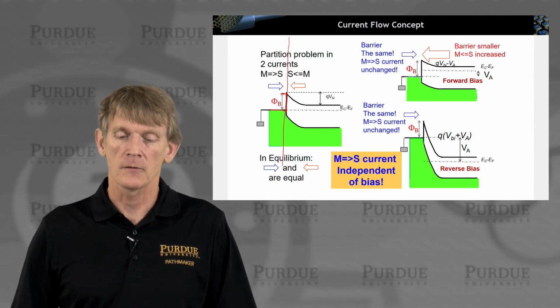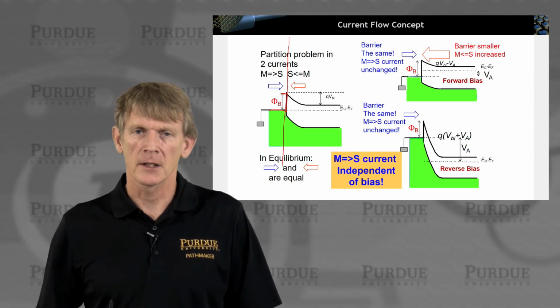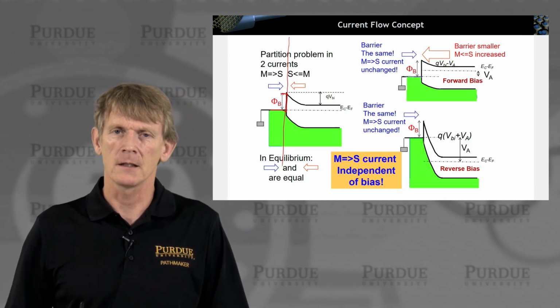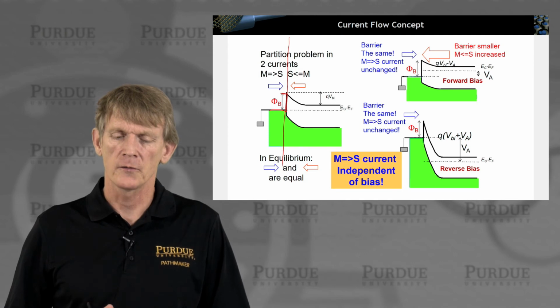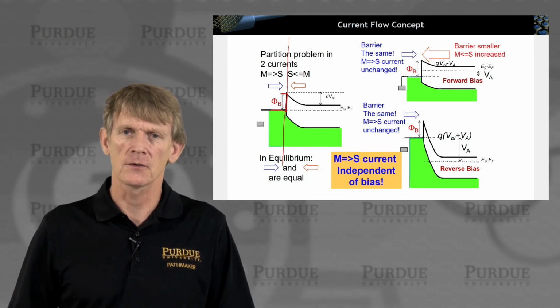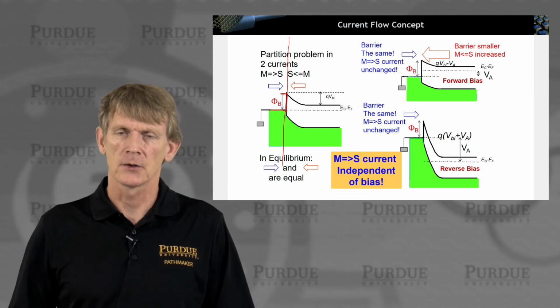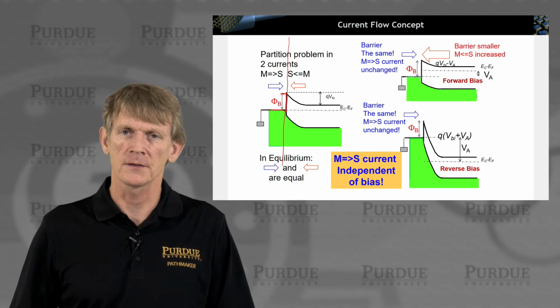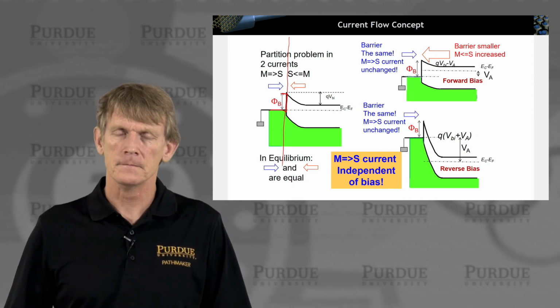All right. Now, for the electrons coming in from the semiconductor and being injected in the metal, that is different. So for the electrons, the barrier of flow from right to left in this graph is going to be lowered. So there's going to be more thermionic carriers available to transition across that barrier, and electron flow will increase.